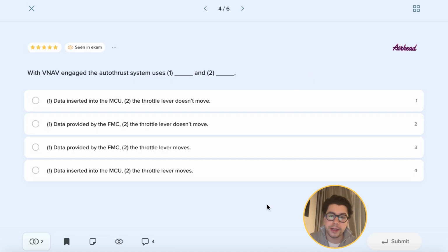And I'll also note here that this automatic system is much different when we're talking about the vertical speed selected, where the aircraft tries to maintain our vertical speed and disregards our actual speed, which, if unmonitored at higher altitudes and over prolonged time, can cause stall. And these questions are very often asked during the EASA ATPL exams.